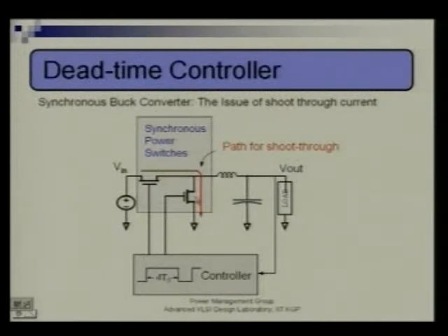Say this configuration, we call it the synchronous buck converter because it has two switches. There is something called the asynchronous buck converter, in which the second switch is replaced by a diode. That one will be taught to you first, I think it has already been taught. Power electronics is over in, say, second year. Oh, it has not? It's in third year. Okay, so you will be taught the diode one. That we call asynchronous.